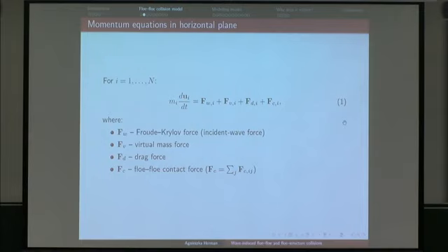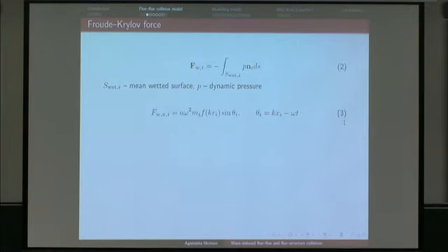And I'm not going to talk more about the added mass. In all simulations that I did, I used a very small value of the added mass, but in fact, the same things that I'm going to say within the next 5 minutes are valid for the added mass force as well, namely that it's not floe size independent. It should be calculated differently for large and small ice floes.